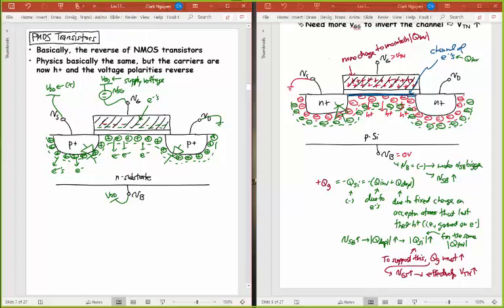So if I raise my negative charge in the gate, you see I'm making some of the negative charges red here. What that's going to do is eventually it becomes more difficult to create positive charge out here, far from the gate. And so what happens is you create that positive charge very close, and these will be holes. And some of those holes you could just steal from the source or drain in this case here. And so this part here is a channel of free holes, which you'll get in the linear or saturation region.